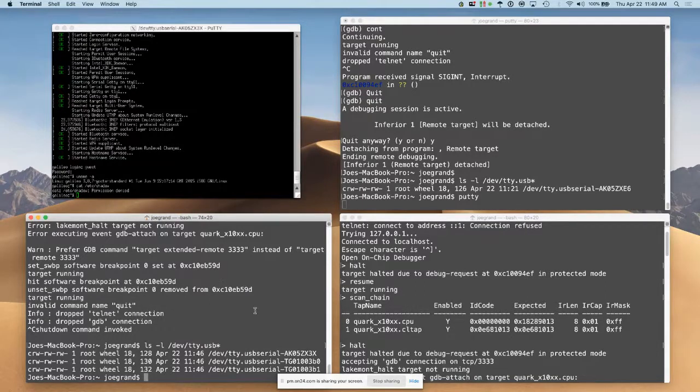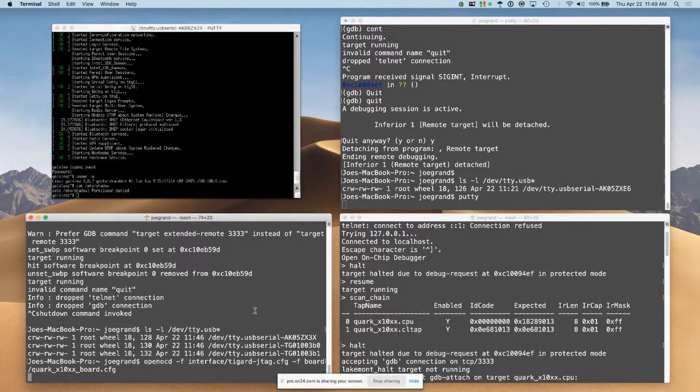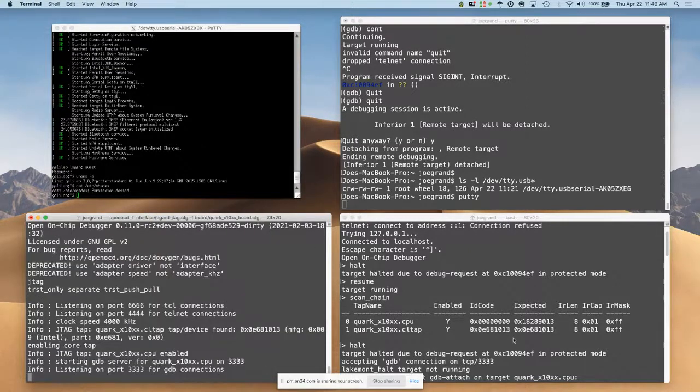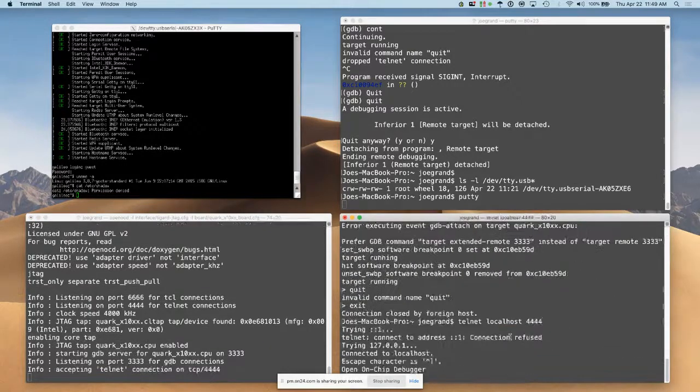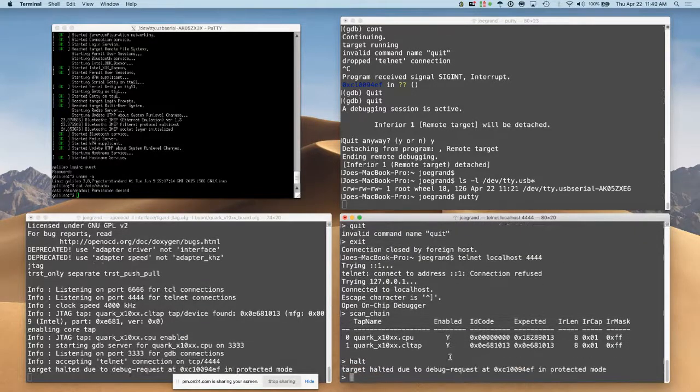So we're going to use OpenOCD to connect to the Tigard, to the Galileo. And now we see we're connected. Then my next window is going to be our interactive window over here. Move this out of the way. Okay, so from here, we can actually take a look at the system we're connected to. We can halt the system. So now we're controlling the microcontroller on that Galileo.